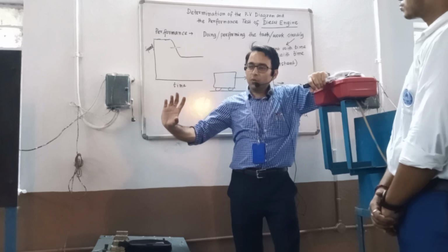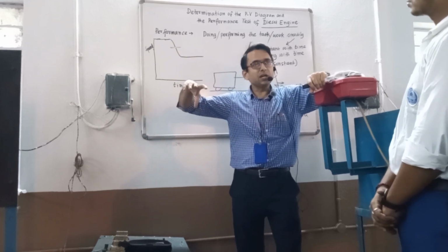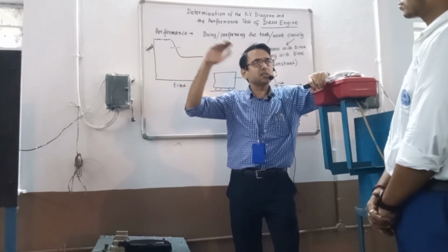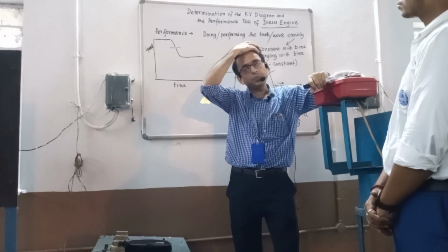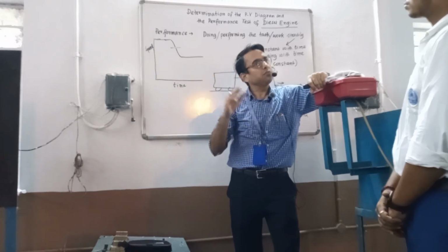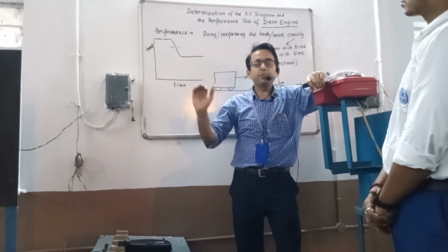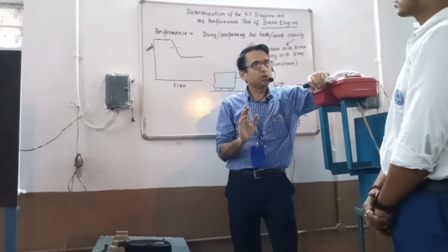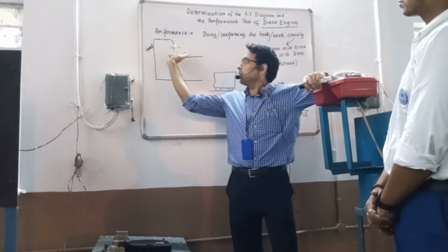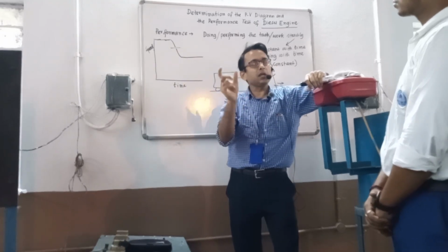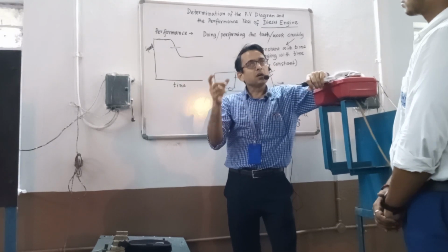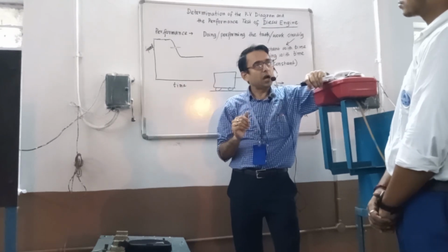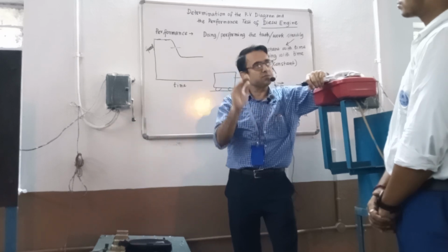This is true for the engine also. When I apply load, it will become steady. Say initially at no load, it was running at some speed, say 1500 RPM. After I apply load, it becomes, for example, 1460 or 1465. So I have to allow some time. Immediately after applying the load, I will not observe the readings.